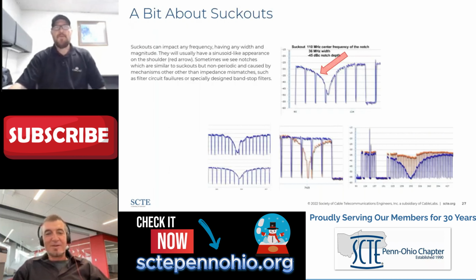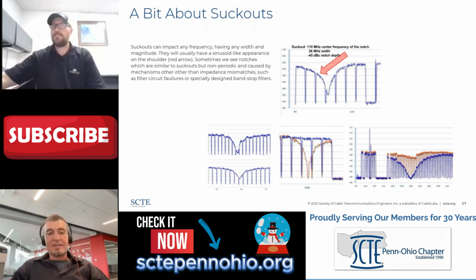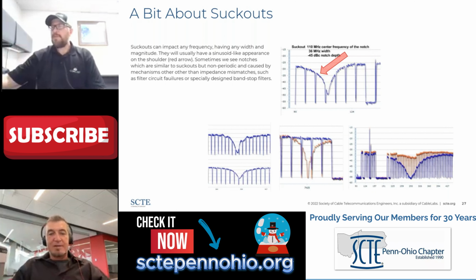Great tip, love it. Another thing about suckouts is that we describe them in different ways. They have generally a center frequency, and that's where the null is, the maxima of the null, and how wide it is, and what's the magnitude? How deep down does it go from the signal?